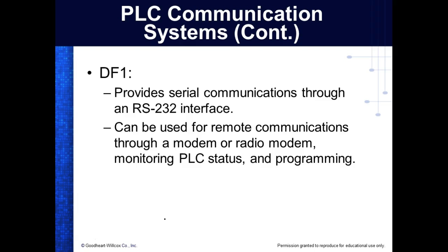This is Wi-Fi, guys. Broadband means you have multiple devices on the media at the same time. To do that, they have to do something called modulation. They take the information and place it on what we call a carrier. And then each one of you has your own carrier. So multiple devices share the bandwidth at the same time. The act of taking information and putting it on a carrier is called modulation. The act of taking it off the media and splitting it back out is called demodulation.